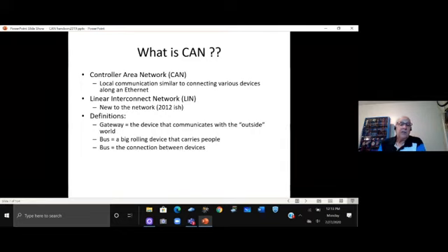The bus is the interconnection or connection between devices. And it can be a single wire or it could be a twisted pair. The most common thing we have now is a twisted pair. First of all, why is it a pair? Well, we have data going out at such high speed, and we have all these different modules listening and talking and everything else, that a pair of wires just works better. There will be exactly the same signal on the 2 sides of the twisted pair if everything is okay. And we'll get into that a little bit also.